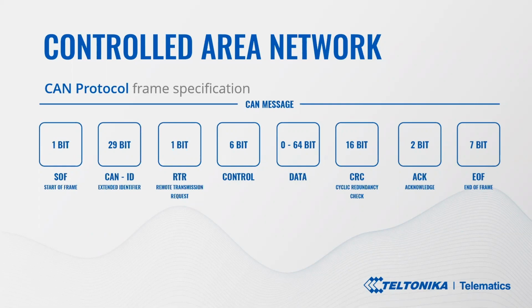However, each network node has a unique identifier. Different parameter IDs may be used. There are also differences in data byte order, offset, signal count in one message, and other differences. Therefore, in order to be able to decode the data that is being sent and read the parameter values from different types of vehicle models, it is necessary to perform reverse engineering tasks.